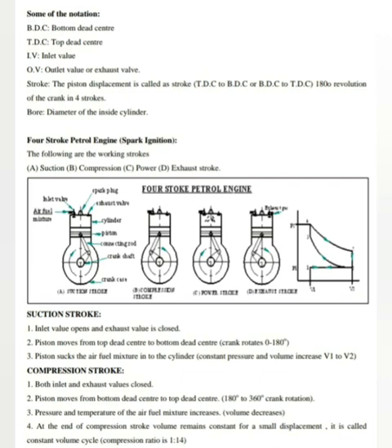The next topic is the four-stroke engines. The working cycle is completed in four different strokes of the piston, or two revolutions of the crankshaft. The four different strokes are the suction stroke, compression stroke, power stroke, and exhaust stroke. Four-stroke engines are commonly classified based on the type of fuel used: the four-stroke petrol engine and the four-stroke diesel engine.